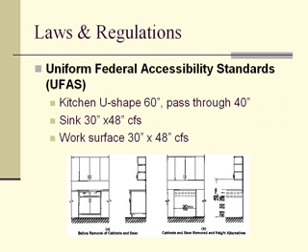There are specific requirements for sinks: the supporting structure should be no more than 2 inches, and the sink should be no more than 6 inches deep, to be able to provide access. The height can also be adjustable, with 28, 32, and 36 inches as options other than 34, but primarily the one mostly utilized is 34 inches.